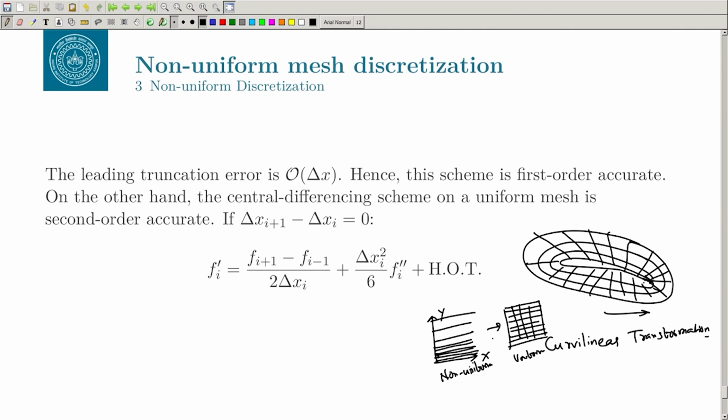Between them you can use a transformation, and you will get a Jacobian which maps each grid point to the grid point in the uniform mesh. The advantage is that you can use all your derivations on the compact schemes on this uniform mesh, calculate the grid metrics and Jacobians, do the calculation on the uniform mesh, and do the back transformation to get back to your non-uniform mesh.